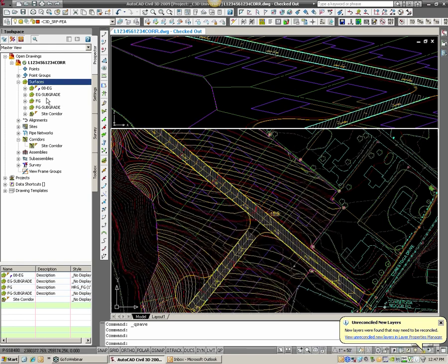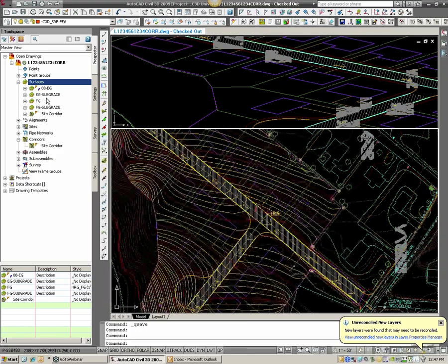So why did I make these 2 surfaces? Well, typically when you're doing a cut and fill volume, they're going to take the topsoil off the existing grade. They're going to stockpile it somewhere. Then they're going to go in and do their mass earthwork, which is what we're looking for volume on right now. And then they're going to take that topsoil and either sell some of it or spread it out on the site, or put it on the lawns first as much as they can, and then get rid of the rest or use it somewhere or sell it.